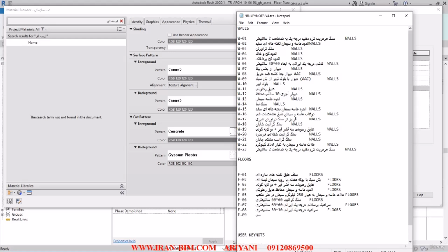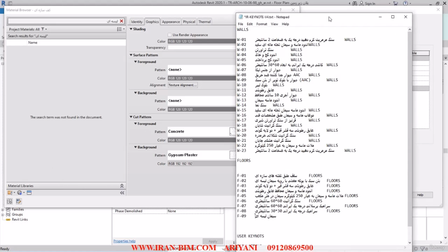So let me see what we should write here. I knew it's smooth cement, but let me take a look at the detailing that we had. It's smooth cement for waterproofing bed. So let me just type it out here. And after we've done that, I hit tab. And then after that, Control V to paste the floors again, and then I'll save it.